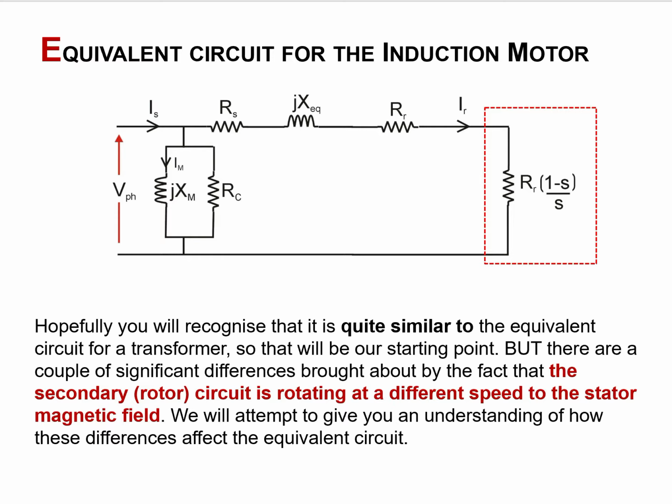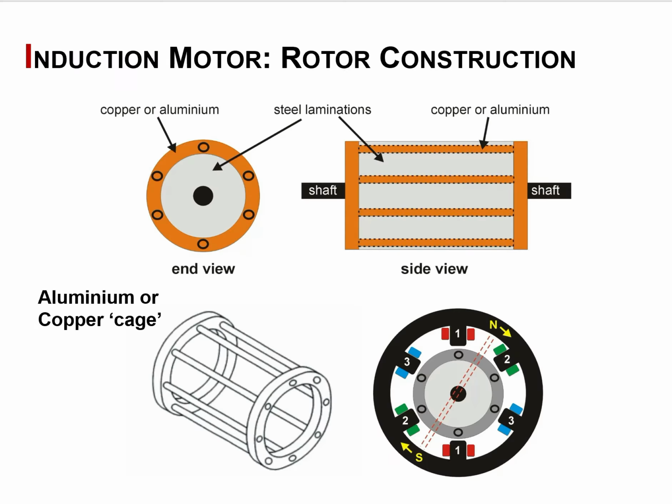So notice that the losses are modeled just by an inductor and a resistor. The copper losses occur in the windings, so the winding resistance is taken into account. Also, the winding has inductance, for which there is a voltage drop due to the inductive reactance, and also a term called the power factor comes into the picture that we will discuss later on.